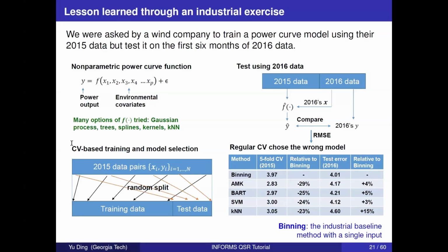And they can measure all these environmental covariates through that measurement process. On the wind turbine, they usually only measure wind direction and wind speed. But usually they have a met tower, and on the met tower they measure other things. They measure wind speed at multiple heights, and they can calculate the turbulence. They measure temperature and pressure, and can calculate air density and so forth. They can measure humidity. There are a number of these variables they can measure.